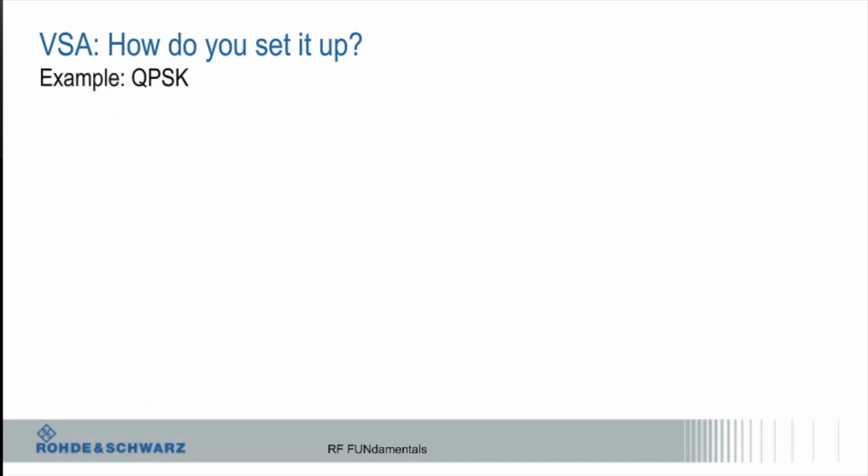So typically, if I was trying to make a low noise receiver and I needed lots of gain, I'd put an amplifier here that had a really low noise figure and fairly high gain. But then when I got to this one, I don't care as much about the noise figure because the gain of the first one is really hiding it. So you see here, when I get the overall noise figure, the first one is directly that, plus you're adding the next one minus 1 over the gain of that.